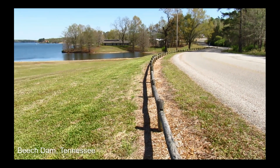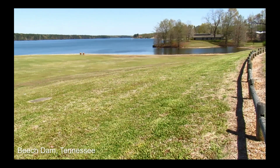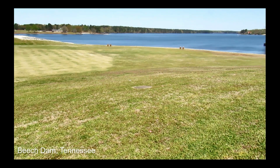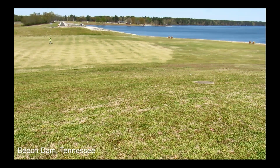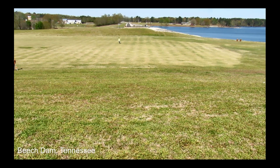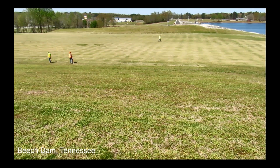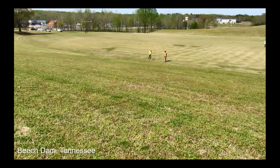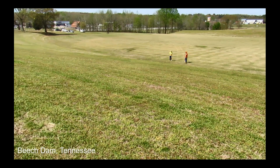Here's a video of a very large grass-lined earth-cut spillway. This one is Beach Dam in Tennessee. And this is a very wide spillway. Now, with a lot of the auxiliary spillways, when they start to get this width, you'll sometimes see a splitter dike within the spillway to divide the flow. This spillway does not have a splitter dike.